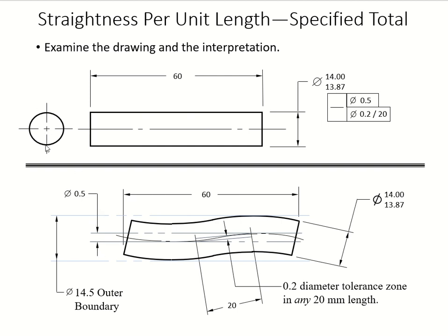You can see only a circle and that diameter, because we're dealing with the diameter right here. You can see this little symbol. That's a 14.5, yeah, outer boundary. Yes, that's because you can go all the way to 14.5, yeah, with your tolerance given to you. Okay.